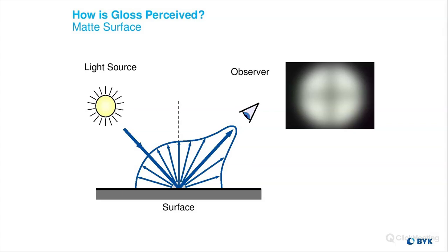Absolutely. Cool. In your experience, how does gloss impact the color measurements using multi-angle spectrophotometers? So it depends. Gloss will affect it depending on the type of geometry that you're using. There are two different types of geometries to measure color: the 45-0 and the sphere.